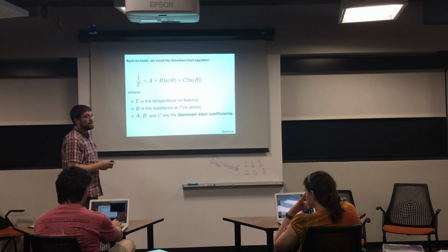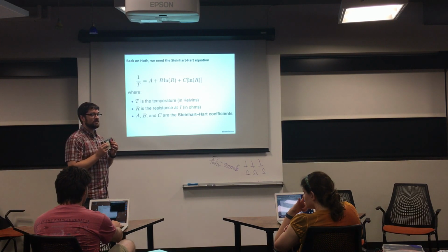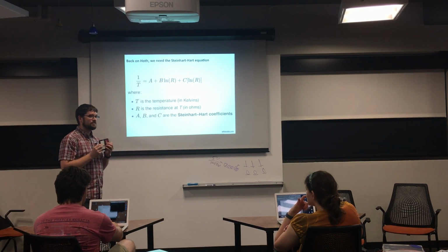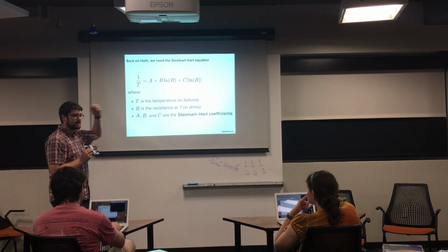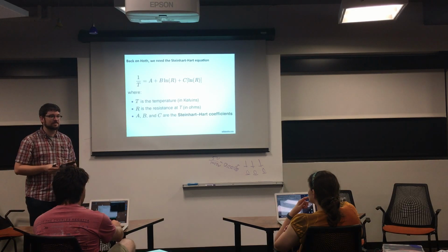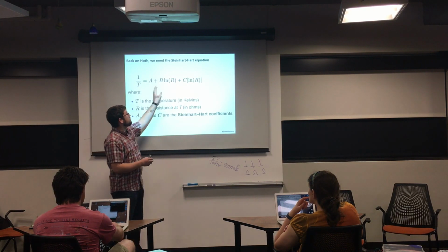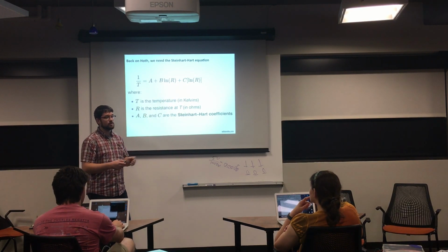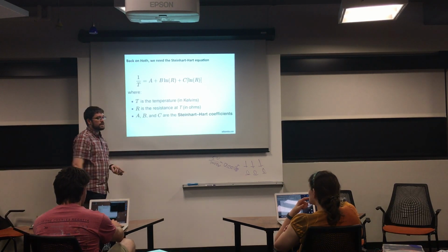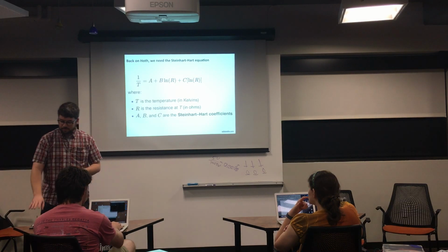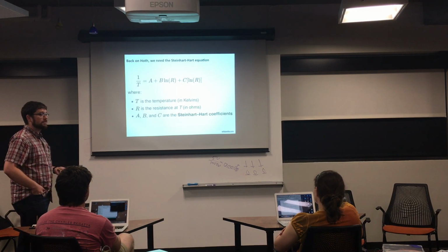It's not that hard, but if you try to do everything on board in Arduino, remember, this is an 8-bit processor that kind of has fake floating point math. It thinks of everything as integers, really. So try taking a natural logarithm with no integers in an 8-bit processor. It can get pretty tricky, though we've got ways to do it. For example, some of these processors have log tables stored in permanent memory, so you can look at the log table and have a successive approximation. But regardless, you can implement this equation either on your computer after you record the data or there. And we would get out the temperature on Hoth. Probably very cool.